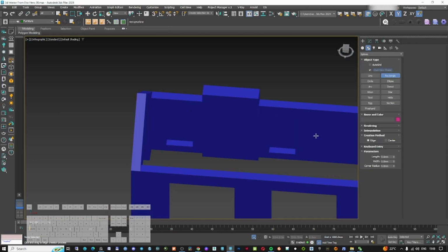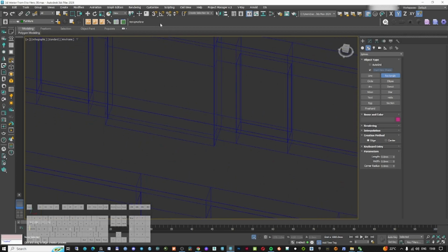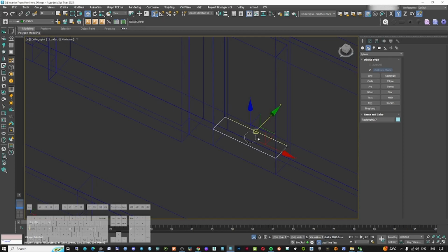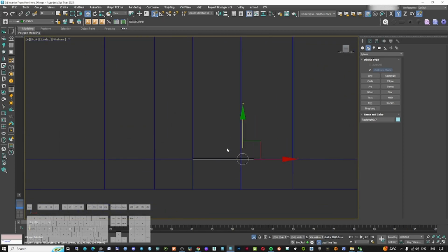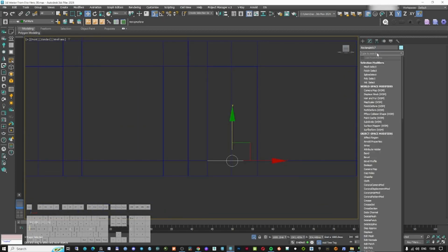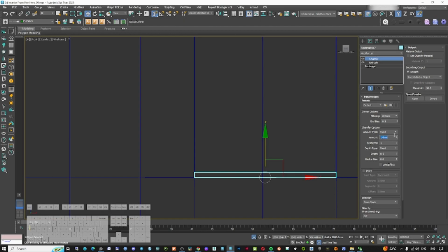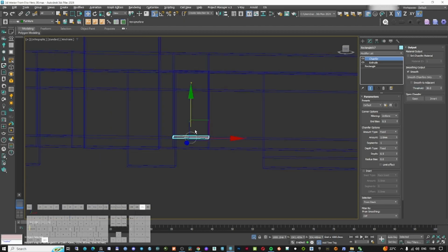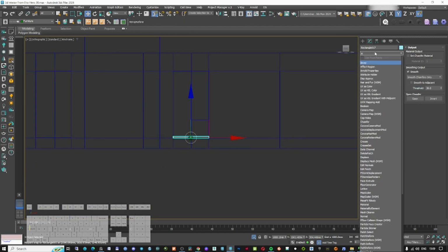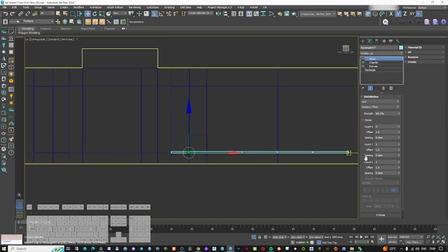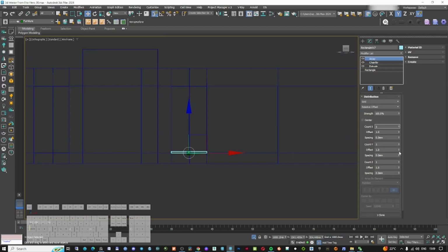Okay, then here I need to create the shelves. I'm just going to create them on one side, and on the other side I'm just gonna copy this one. So because I need shelves on all the height, I'm gonna extrude this. I'm gonna make it 35 millimeters. I'm also going to use a chamfer to smooth the edges. Okay, this is looking good. And then I'm going to apply an array, of course, and on the array, not on the X, only on the Z.